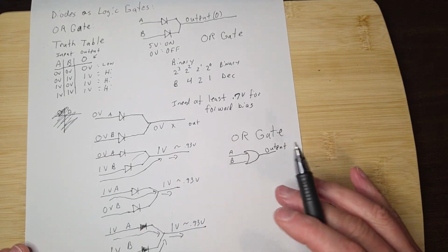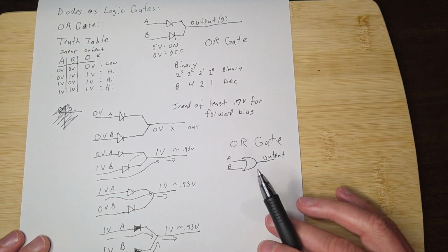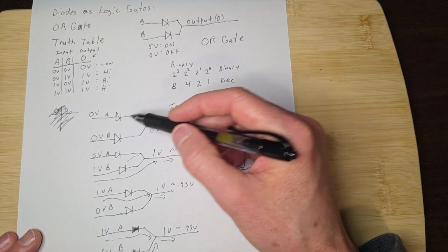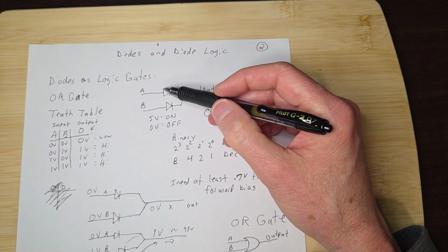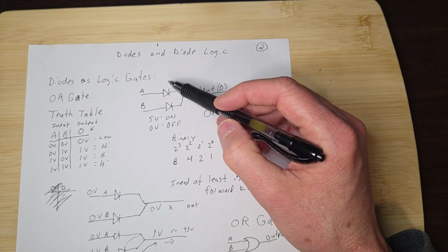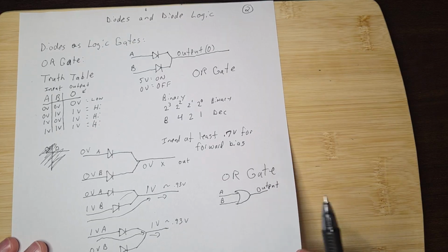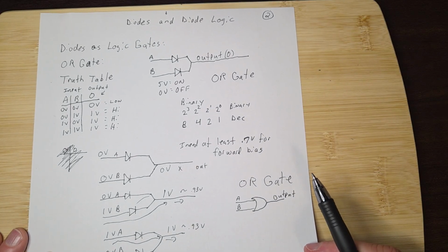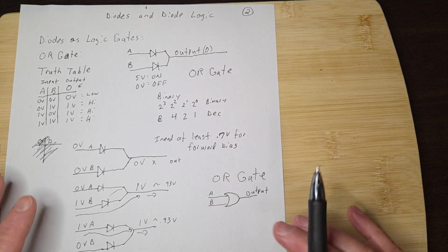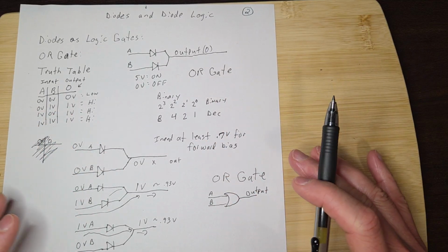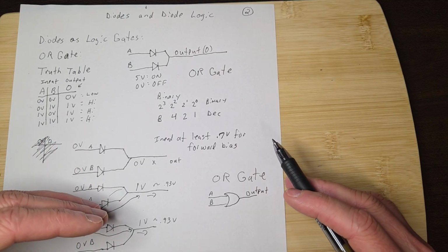But it's kind of cool to think about how people probably used these a long time ago. Before they had ICs, they had to use discrete components, and then transistors came out, and you can do a transistor the same way. A transistor can be a switch, or it can be used to amplify things, but you can have a transistor just turn on and off, kind of like we're doing here. Okay, so I think that gives you an idea of how a logic gate works, and you can apply this to different gates: there's AND gates, OR gates, NAND gates, NOR gates.